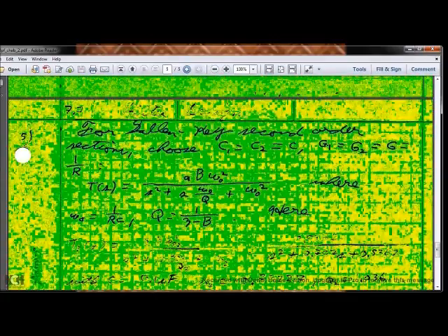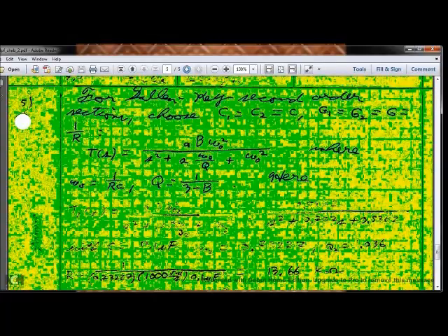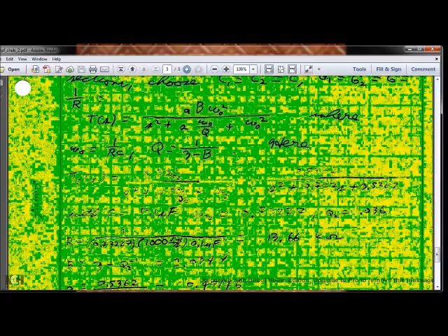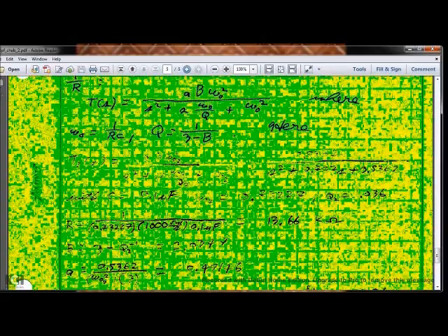For the second order biquad, Sallen-Key second order sections, set C equal to 0.1 microfarad. And here is a T of s. We're breaking our numerator into these factors, A, B, omega 0 squared. And there's reasons why, because we can derive some of our other values from that. Q, the quality factor, is equal to 1 over 3 minus B. And I'm sorry this didn't show up very well.